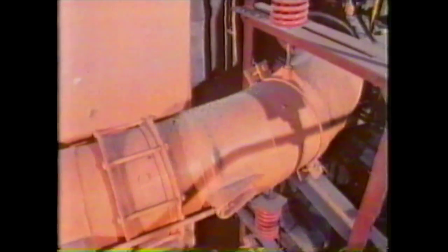It's drawn in from outside, and here's one of the huge ducts down which it comes. Each of the 4 boilers has 2 furnaces, supplied with air in this way. There's one of the big electric fans which draw in the air. The coal dust is blown along these orange-coloured pipes to be injected into the furnace. Every 10 minutes or so, a ton of coal is burnt at each burner.